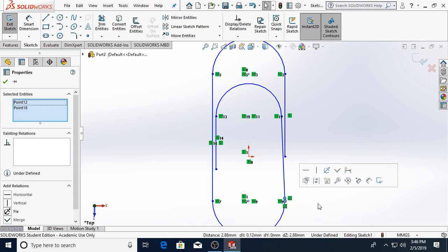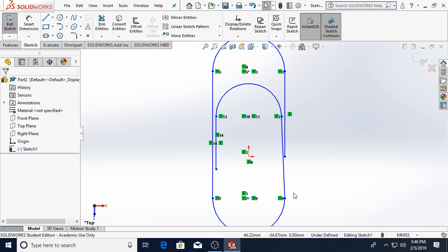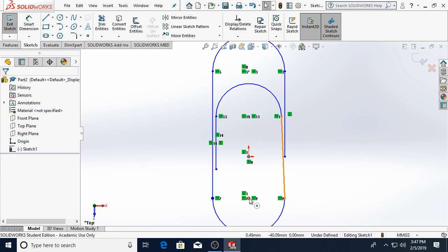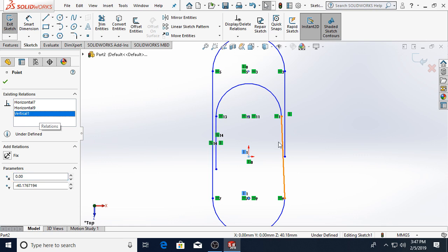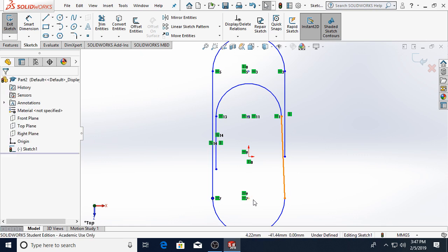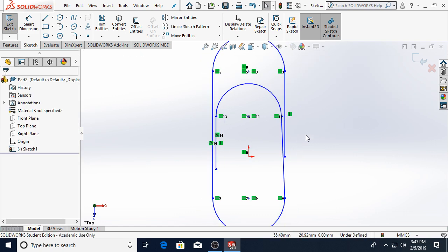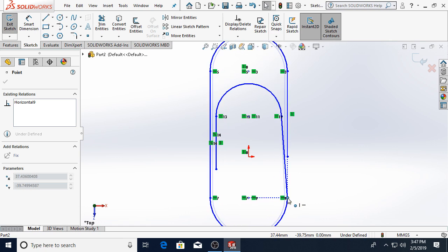Speaking of games that I'm playing, I seem to have a bit of an issue here on the right side, but I can fix that issue by getting rid of this vertical position. So I had the bottom circle positioned vertical relative to the origin. Now I can make that right line vertical and I don't break any rules of geometry. He said, in the process of breaking rules of geometry.